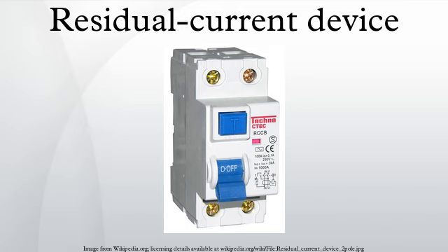There are also RCDs with intentionally slower responses and lower sensitivities, designed to protect equipment or avoid starting electrical fires, but not disconnect unnecessarily for equipment which has greater leakage currents in normal operation. To prevent electrocution, RCDs should operate within 25 to 40 milliseconds with any leakage currents of greater than 30 milliamperes, before electric shock can drive the heart into ventricular fibrillation, the most common cause of death through electric shock.